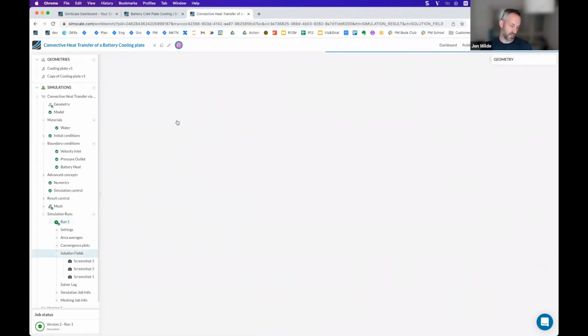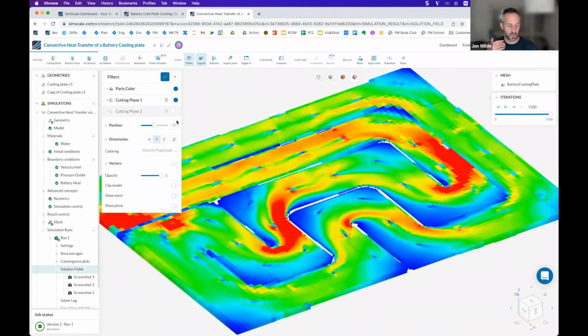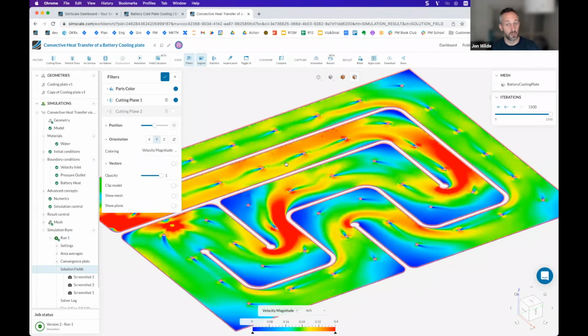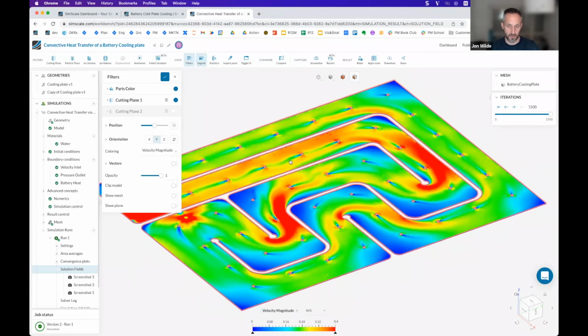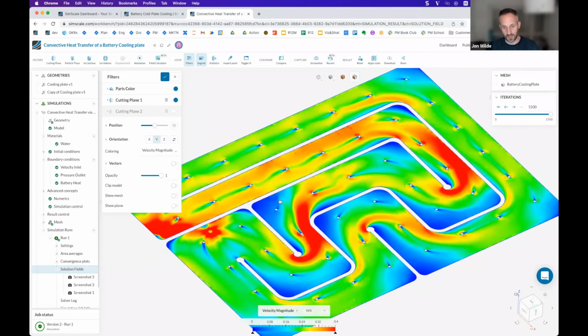Instead of the other simulation, which took a couple of hours to run, this takes something like 15, 20 minutes, which means if you're going to do it step by step, iteratively, you can do it much quicker. So you can get insights much faster. The results look broadly similar, as they should, but we can see the flow still comes through. Turbulators aren't doing too much, apart from stopping the flow moving through the center and letting the cells beneath get warmer. But otherwise, everything is very, very similar.